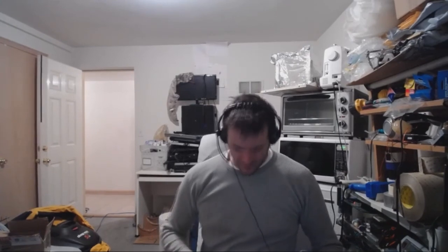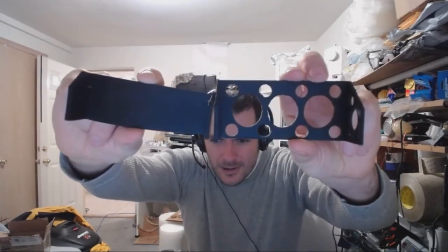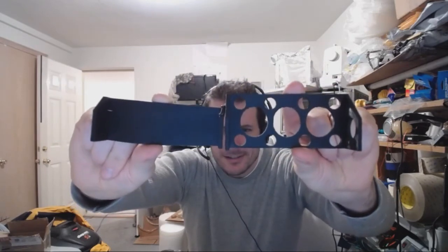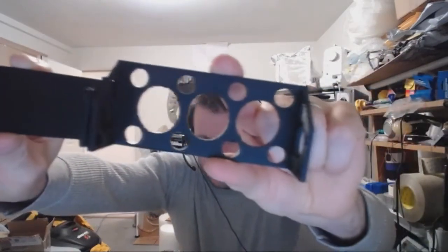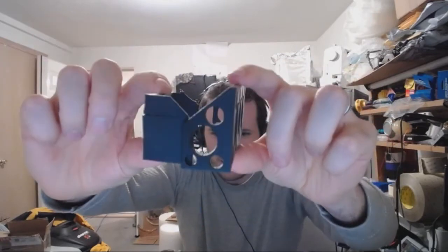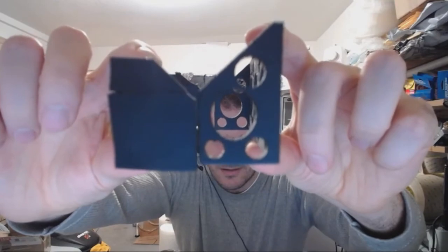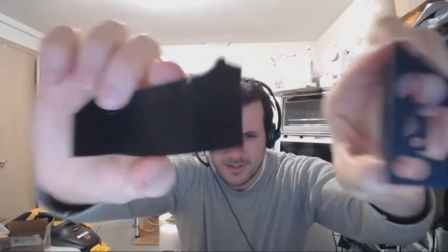Alright guys, so this is the difference between a model with no holes in it. This is supposed to be totally flat on the bottom. Look how warped that is. And then here's how it's supposed to look. They look nothing alike. That's sad. This is the same exact model. Look how clean the holey one is. That's why we add the holes. Because everything gets screwed up if you don't. So that's a proof. And that's with the same printer, same everything. So I'm definitely going to be putting Swiss cheese holes in all of my stuff from now on.